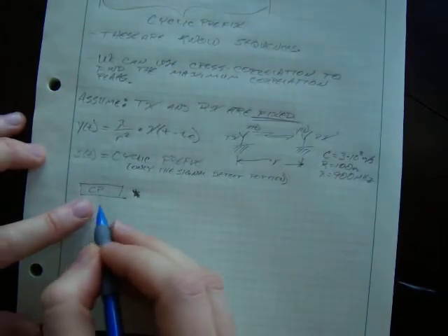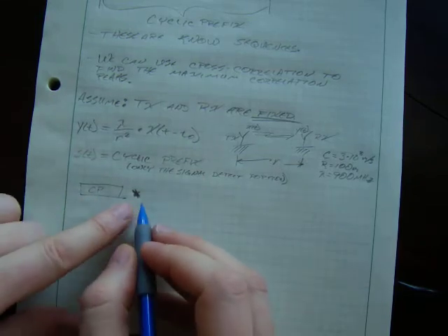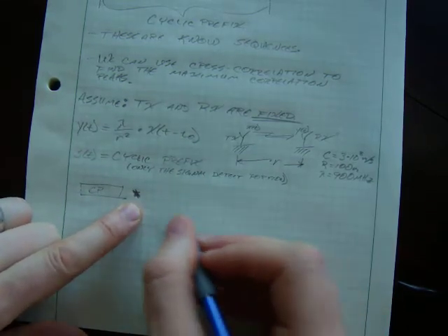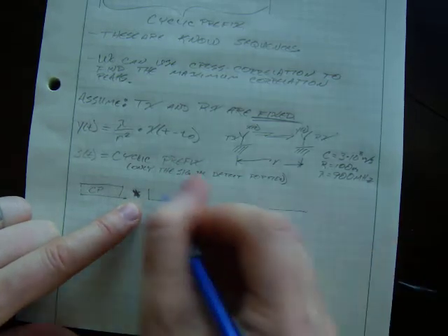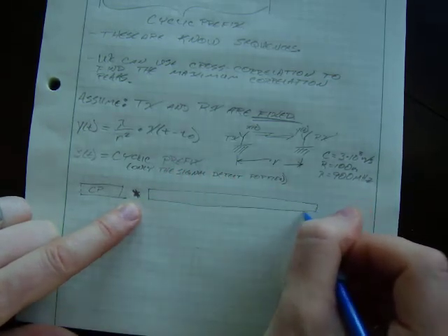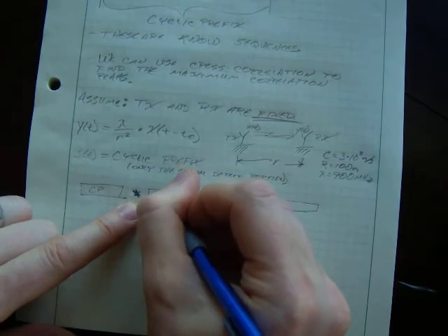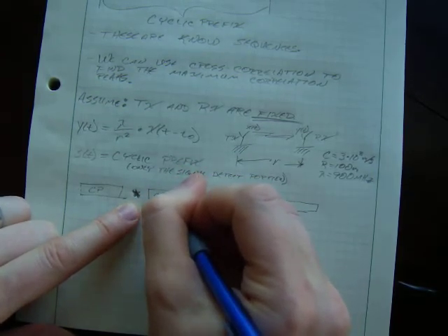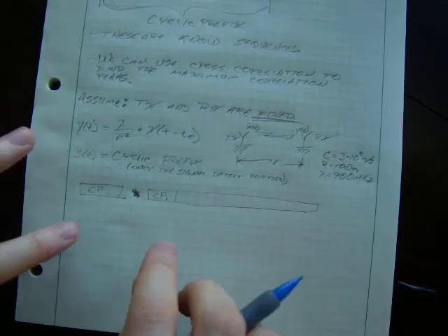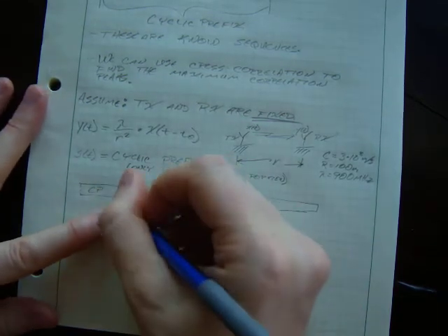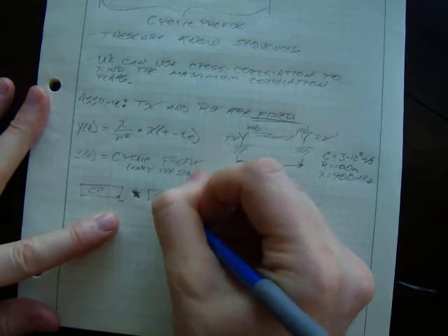And so we're going to take the cyclic prefix and cross-correlate it with the incoming data stream. And the incoming data stream is going to be some modified value of the cyclic prefix, and I'm just going to denote it CP1 to differentiate, and these should be the same width.